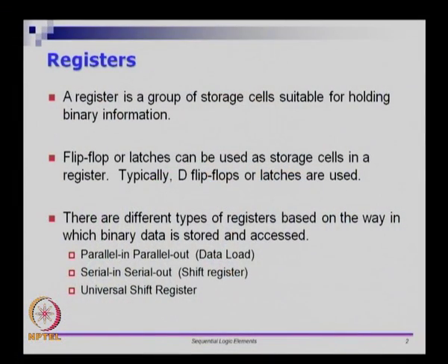We saw the basic building blocks, namely latches and flip-flops. Particularly we looked at D latches and D flip-flops. So I am going to use D flip-flops and design sequential circuits. The first thing I would like to talk about is something called a register. A register is just a group of cells, a collection of cells, and these cells could be either latches or flip-flops.